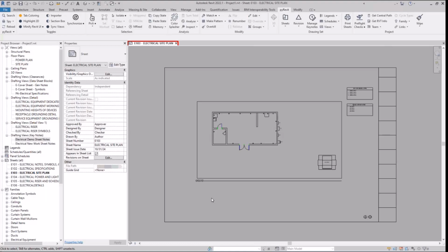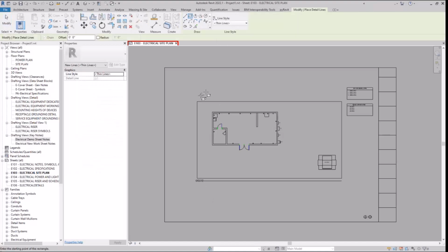I know ANSI, the American National Standards Institute, was trying to push out an actual standard for controls, for instance. These are what control symbols are supposed to look like. But as far as everybody's general note should look like this, keyed note should look like that, demo note should look like that, there's no standard out there that I know of, and it just started from whoever had the brilliant idea. Now, the most important thing is making sure you put it on your legend, whatever you end up using. Exactly.